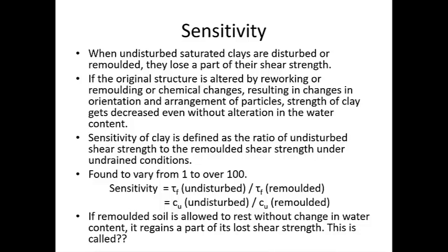So where does thixotropy play its part in soil mechanics or in geotechnical engineering? Where do you see thixotropy? In pile driving or pile boring practices, isn't it? You disturb the soil, you insert a pile, and over time, what happens, that clay will settle back and it will regain its strength over a period of time. So sensitivity is a ratio that represents that strength loss or how sensitive your clay is.